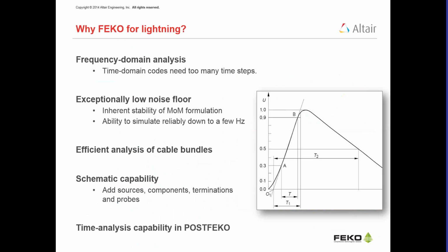FEKO also offers efficient cable bundle analysis, which can be used for coupling of the lightning currents into the cable bundles. We do have time analysis capability in post-FEKO that can be used to represent the data back in the time domain. By the way, FEKO also offers a finite difference time domain solver, which can be used for time domain analysis. But we feel that for the low noise floor that we need, using the method of moments will be the best option for this case.